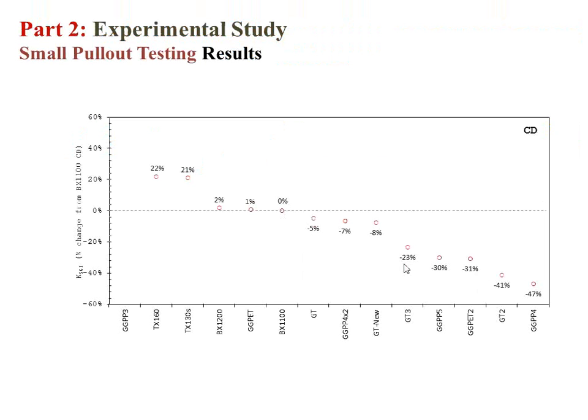So the ongoing testing program that we have going on right now is essentially to identify a standard granular material that we will use as a reference to calculate the stiffness of different geosynthetics, and validate whether by changing within parameters the grain size distribution, we still for sure are going to get different numbers. But are we still getting the same, let's call it ranking? Product A works better than product B, works better than product C. That's what TxDOT wants. And it's great for specifications.